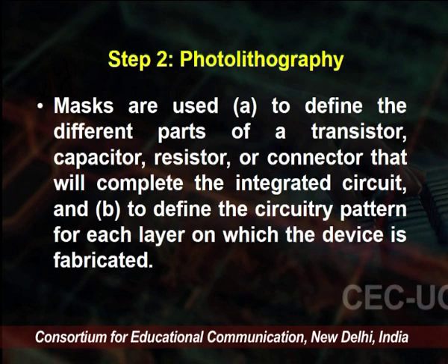At the beginning of the production process, bare silicon wafers are covered with a thin layer of glass followed by a nitride layer. This glass layer is formed by exposing the silicon wafer to oxygen at a temperature of 900 degrees Celsius for an hour or more, depending on how thick a layer we require. On that basis, a thin layer is developed on the silicon wafer.